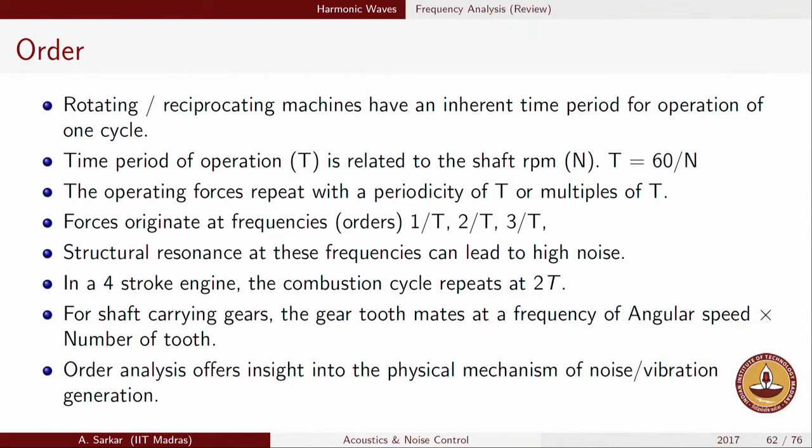And these frequencies are colloquially termed as orders. So, when we say that there are certain orders of your noise and vibration signature in the signal, we say that these are the fundamental frequencies and these are the harmonic frequencies which are present. In order analysis, typically what we are interested in is finding out the nature of the forcing that happens at different RPMs, like the combustion process, for example. Again, for different speeds of the crankshaft, it is going to change. So, typically in acoustic analysis, order analysis is pretty important.